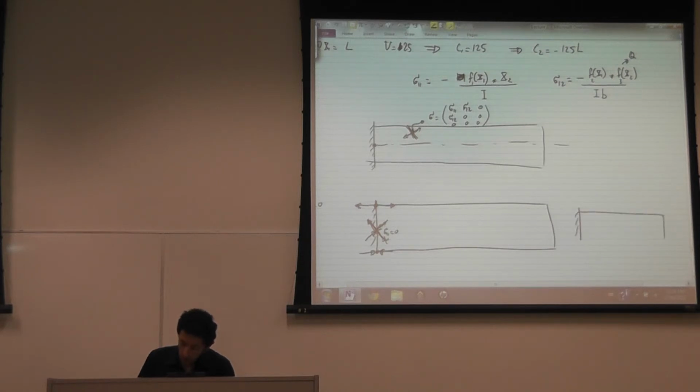So for a cantilever beam, you know that you put tension at the top, you put your steel bars, and tension in this direction. In the past, they used to put steel bars like this to take that diagonal tension. But now, instead of using this, they use the shear studs, vertical, which basically does the same thing.